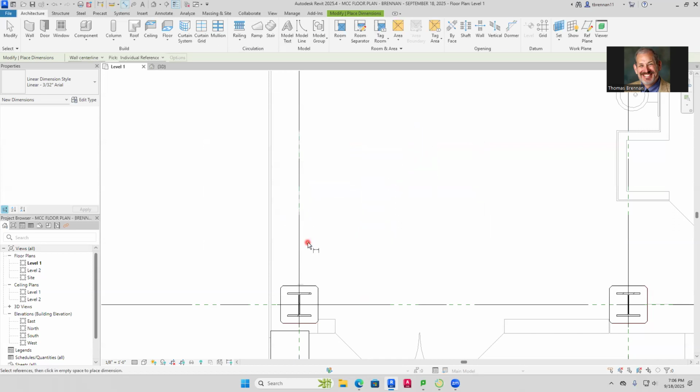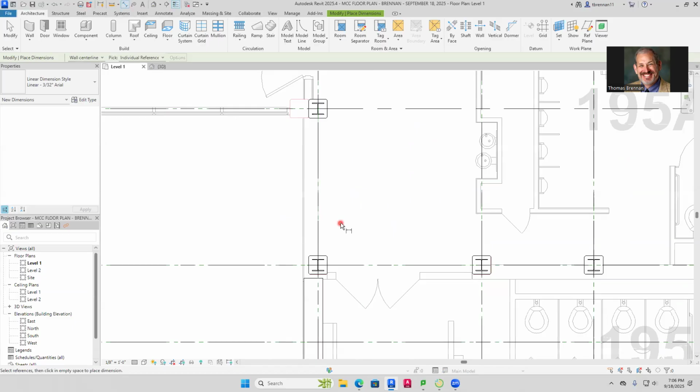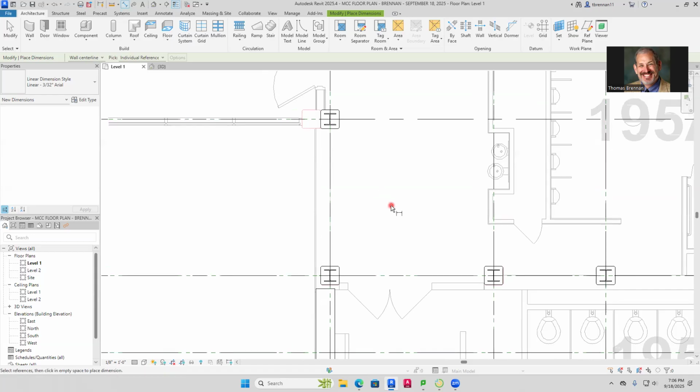How do you fix it if it doesn't let you save it as a project? You can always save it as a different name. You can always rename it. No, it doesn't let me save as a project. It lets me save only as a template. Right. Then save it as a template, and then we'll have to bring that template in and save that. And then you have to start a new project using that as your template, and then you save that as a project. So when you get to that point, just make sure you save it as a template right now. We'll get to that other point later.